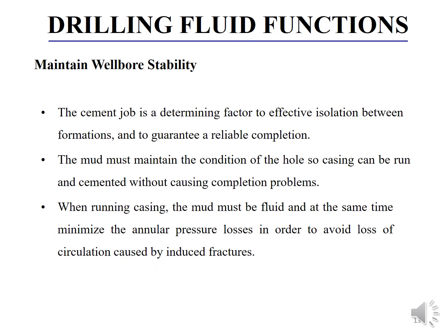So the cement job is a determining factor for effective isolation between the formations and to guarantee a reliable completion. So it is the last step which separates the drilling fluid and also the formation. The mud must maintain the condition of the hole so the casing can be run and cemented without causing completion problems. So when running casing, the mud must be fluid and at the same time it must minimize the annular pressure losses in order to avoid loss of circulation which is caused by induced fractures.